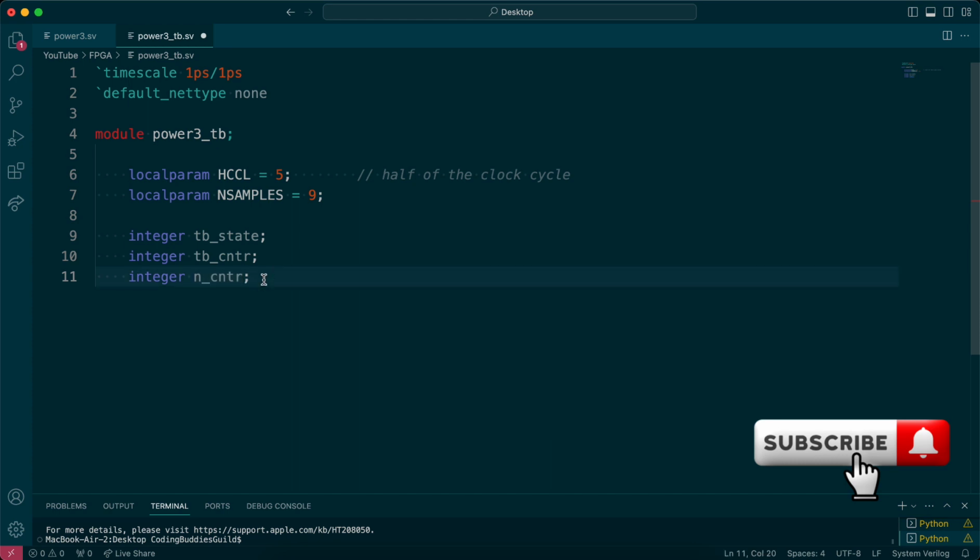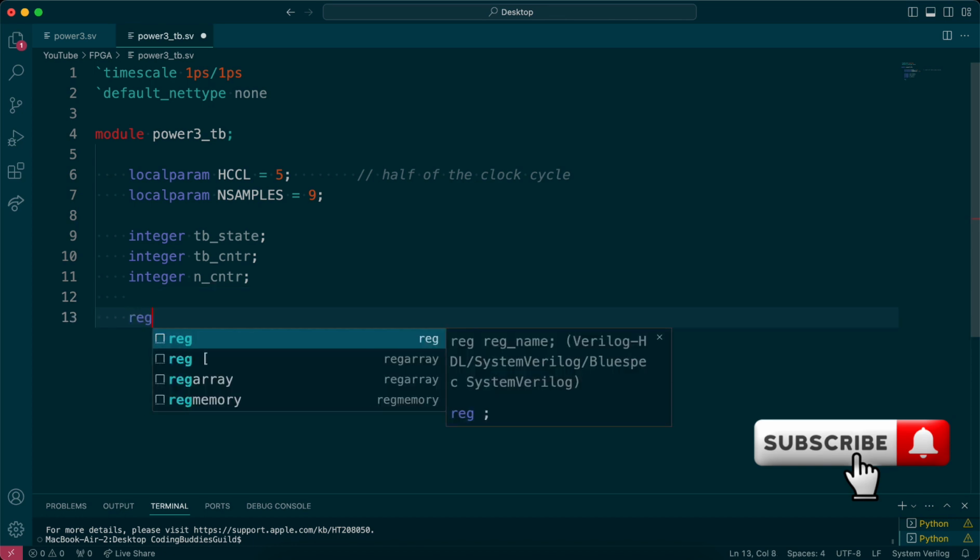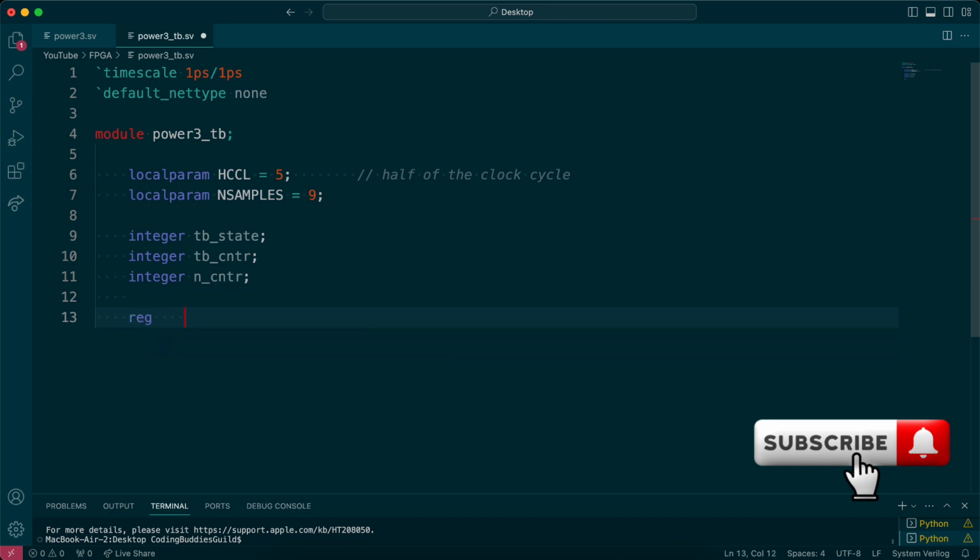So we want to set it to 3, right? And then obviously we have registers, which is clock, right? We can just initialize this to 0, and then we can initialize our clock as well. So clock is set to 0, and we want to have a register. We'll call that reset, and we set that to 0 as well, or we can set it to 1. Doesn't matter really. What matters is how you use this in your TB, right?